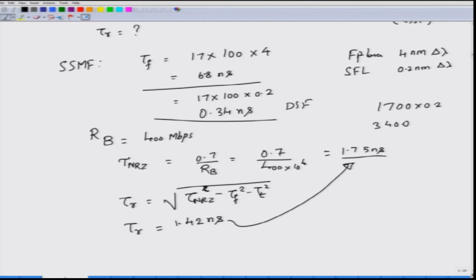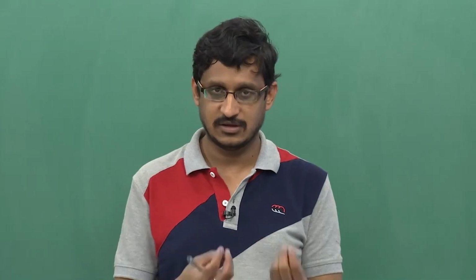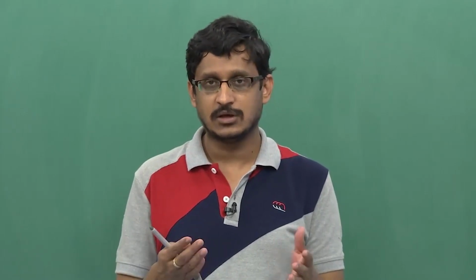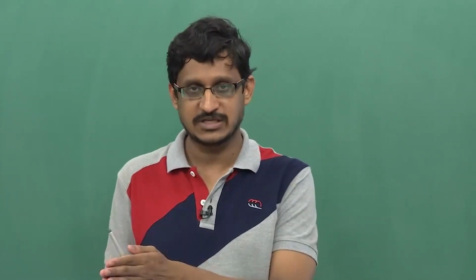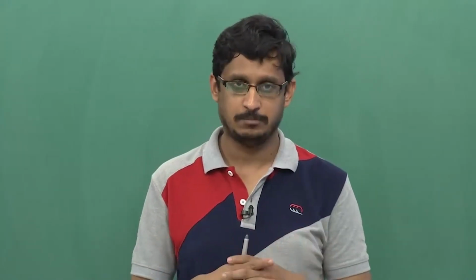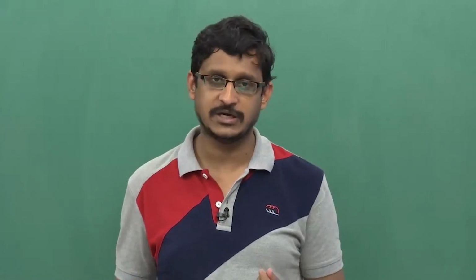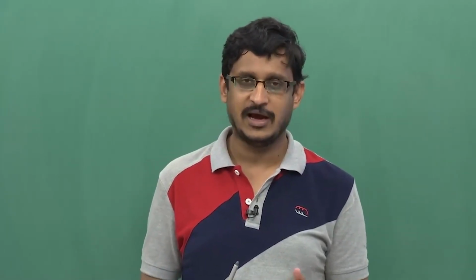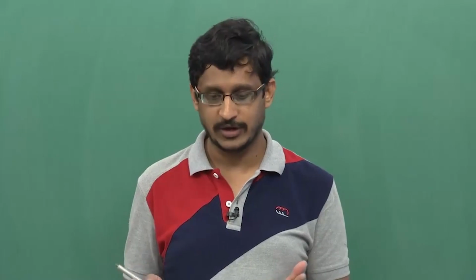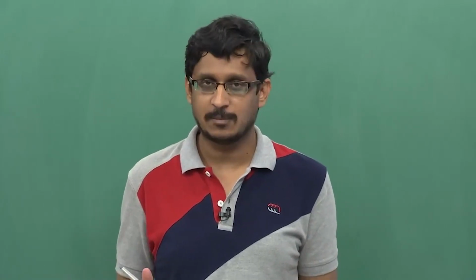So, in this way you have to design the components in such a way that you are transmitting signals at a given bit rate, with the overall goal of maintaining the rise time budget as well as the power budget. For different fibers and different operating conditions, the rise time budget will also change, and you can use MATLAB to calculate all these values. We will supply you with a small MATLAB program which you can use to come up with the maximum value for propagation distance and for the rise time of the system. Thank you very much.